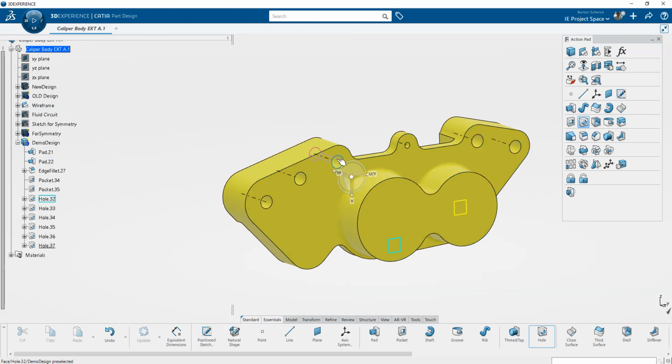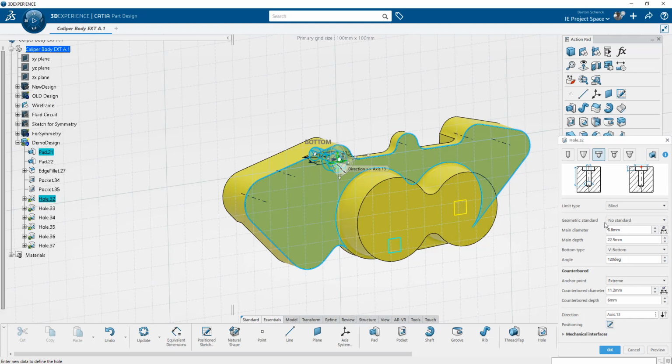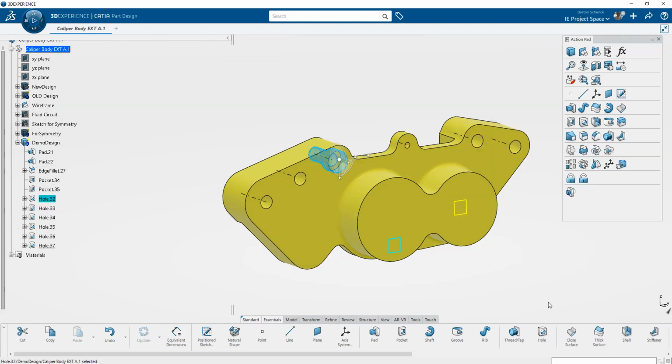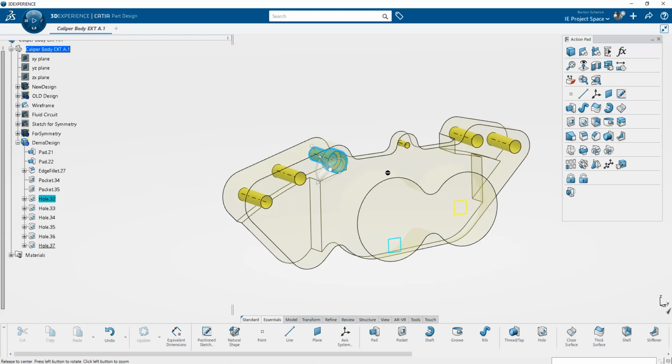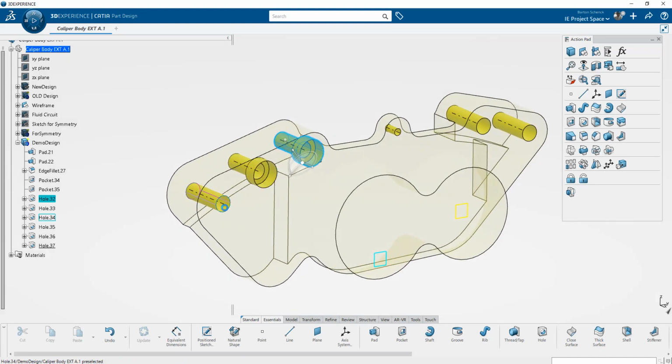Another valuable tool in CATIA part design is the semantic painter. For example, if I change this hole to counterbored, the rest of the holes do not change. However, using the semantic painter, I can select it and then select all entities that I would like to have the same properties as the initial one. Painting format, similar to things like Microsoft Office.